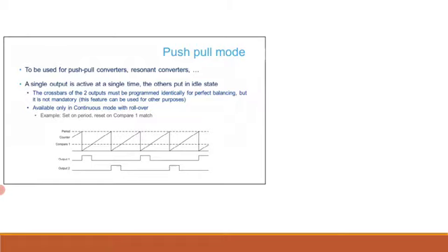In this figure, two identical waveforms are programmed on output 1 and output 2. The push-pull circuitry disables the outputs every 2 cycles, out of phase, so that the signals can be built using a single compare value to set the PWM duty cycle. This is also possible without using the push-pull, but it would be at the expense of 2 other compare registers and a large CPU burden. Finally, it must be noted that it is possible to unbalance the signals and generate asymmetrical waveforms. For instance, a PWM using compare 1 for output 1 and a PWM using compare 2 for output 2.